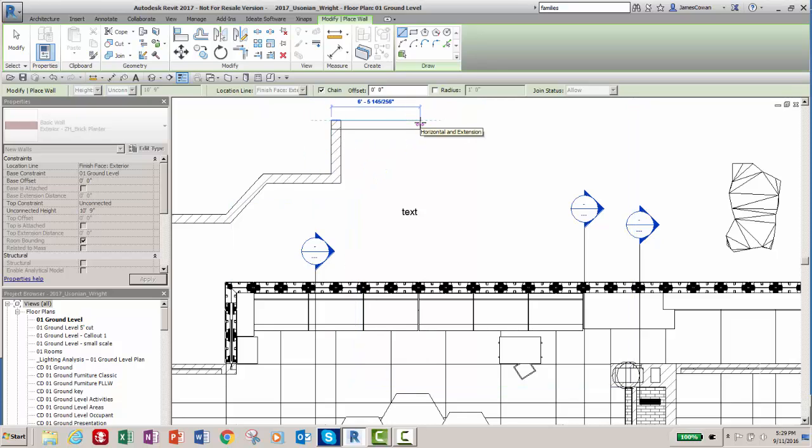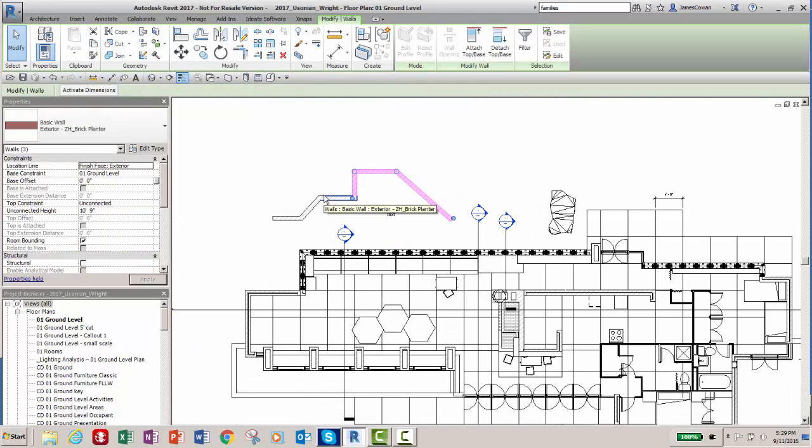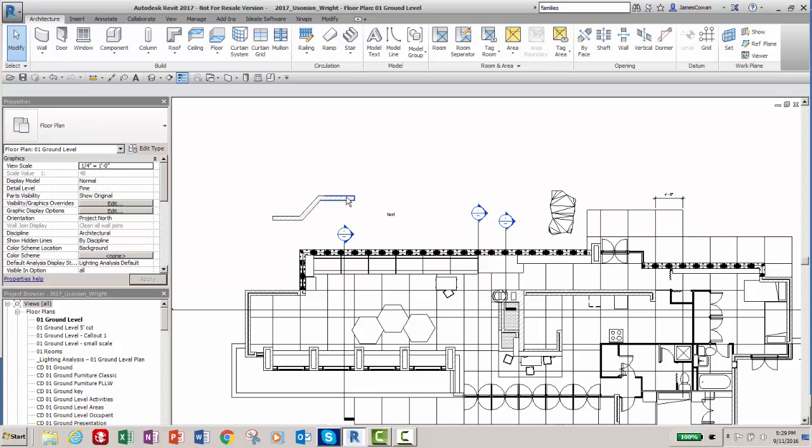If I said something like 2 and I put meters, 2m, I can draw 2 meters length. If I point and I said something like 3355 millimeters, that's exactly what I'm going to get in terms of life size for the units that I'm drawing with. So I think it's a little overstated that setting those values is a big benefit to you.